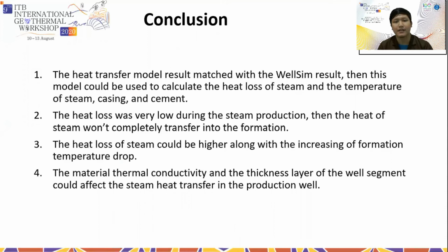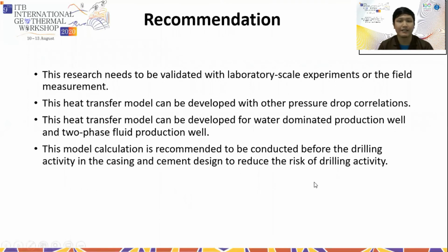And the material thermal conductivity and the layer thickness of the well segment could affect the steam heat transfer in the production well. And then there are several recommendations from this research for further research and the usage of this model calculation. This research needs to be validated with laboratory scale experiments or field measurements. This heat transfer model can be developed with other pressure drop correlations such as the Beggs and Brill correlation, Hagedorn and Brown correlation, or other correlations, and so on.